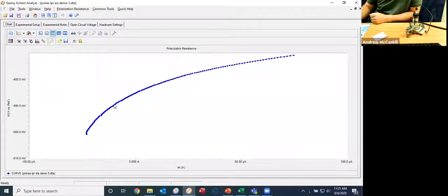And what I'm going to do is I don't want to try to call this whole set of data linear and model after it. There'll be a lot of error involved with that. But if I just select a smaller portion, and I'm going to do it somewhat evenly, both with respect to how many millivolts I'm taking here, or the amount of current on the other side, I'm going to just model this little bit of data right here, and we're going to call that linear and see what kind of values we get spit out. So model it right there. We're going to isolate that.